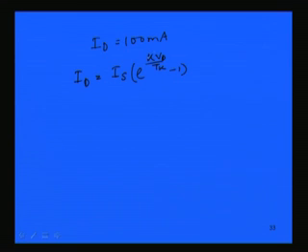Now, for the other part, when the diode current is 100 milliampere, I use a similar expression, I_d equal to I_s into e to the power V_d by (eta) T_k minus 1. Putting the value of I_d here, which is 100 milliampere, we get 100 into 10 to the power minus 3 ampere, with the same reverse saturation current 6.34 into 10 to the power minus 7, and e to the power 11600 V_d, which we do not know, by 300, minus 1.